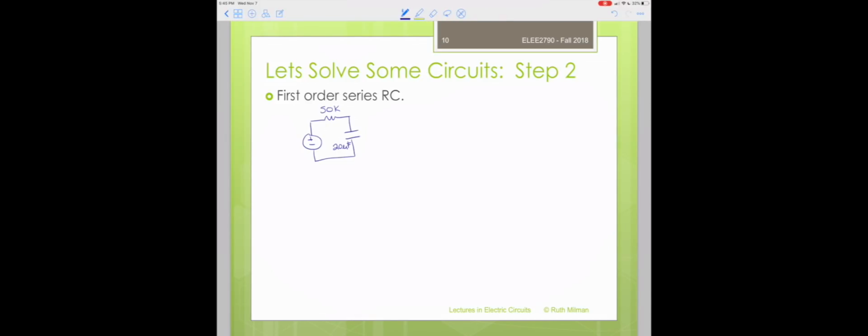Looking at this, we're going to look at the different pieces of the circuit, and the first thing we're going to recognize is what our voltage source is. It has a magnitude of √5, an angle of 45 degrees. Remember, that's the phase shift in the original signal that goes into the circuit. And in addition to that, it operates at 2 radians per second. That last piece of information is critical because we actually don't know what we need to know unless we have that. So converting to impedance, this is our phasor for our input.